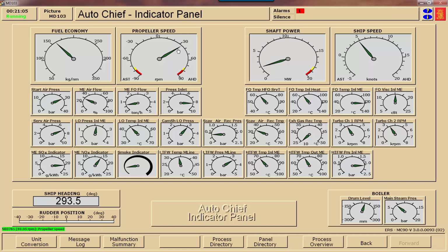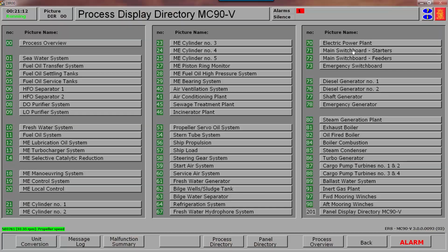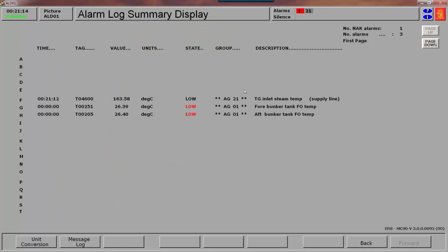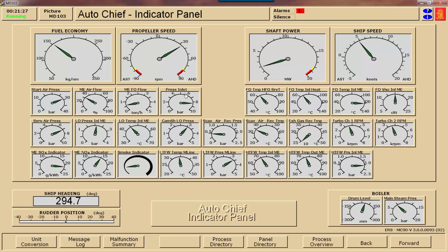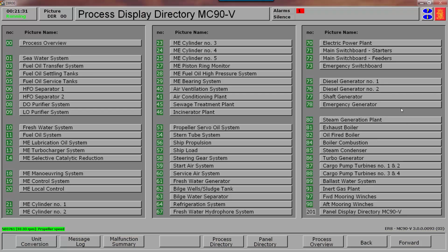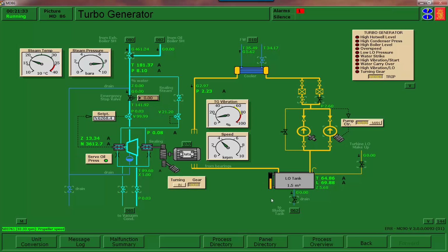Okay, we're still really at dead slow. So we still don't have a lot of energy. Yep, our steam temperature is low. That's again why I suggested that you wait till the engine starts. Okay, our dampers are open. But again, that energy for that exhaust gas boiler is coming off, and we're still really at dead slow. So not a lot of energy available right now.